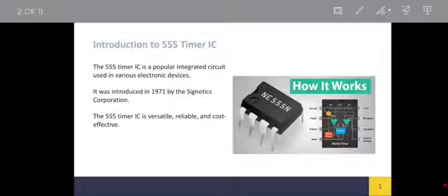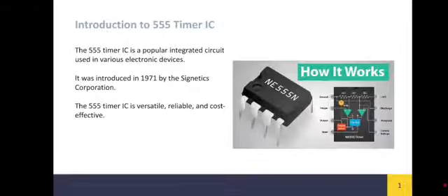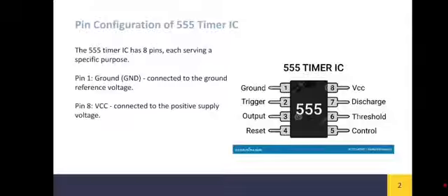Let's move to the pin configurations. The IC555 timer consists of 8 pins and each pin has a specific function. Pin 1 is the ground pin, and it is connected to the ground reference voltage. Pin 8 is the VCC. It is connected to the positive supply.